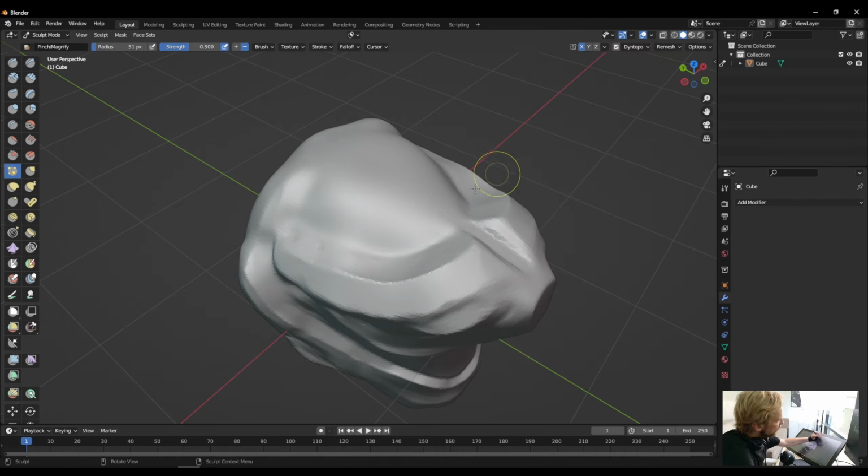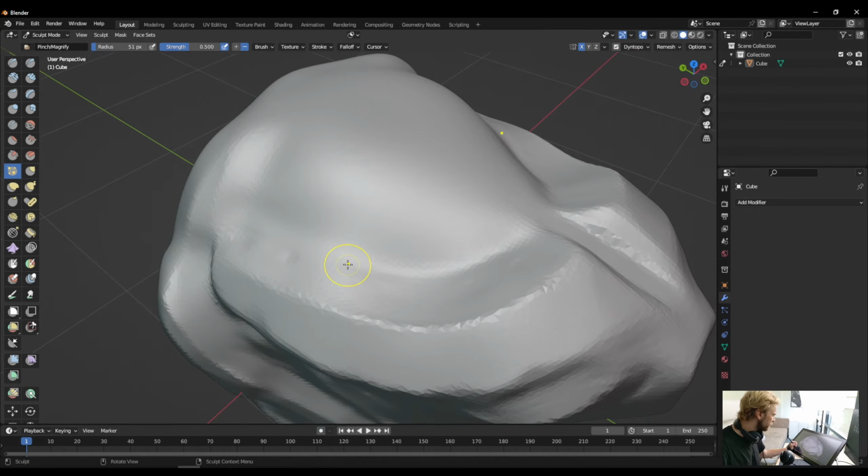But instead of relative detail, I prefer to use brush detail and then change the percentage of the size of the brush. So let's say with 25, you can see that the amount of polygons basically is similar to 4 pixels in my case.